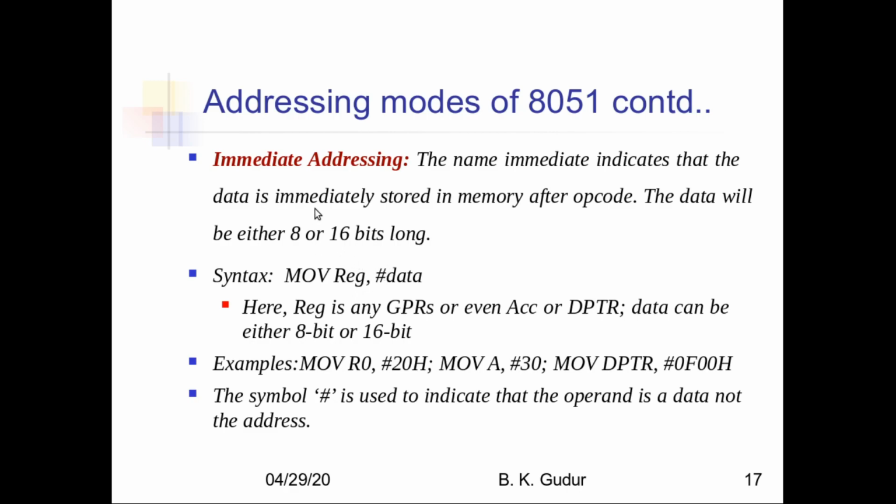I hope why we call this particular addressing mode immediate addressing mode is clear to you. The simple thing is, when we write a program, during assembling the program will be converted to opcodes, in hexadecimal code, where the mnemonics are converted to opcodes, and immediately after the opcode the data or operand is stored, which will be used for the operation.